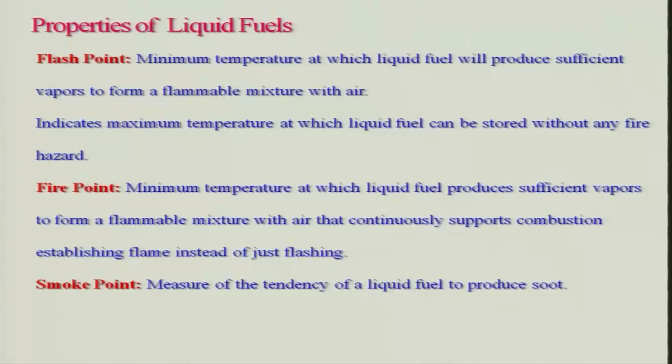Another property is known as smoke point. It is a measure of the tendency of liquid fuel to produce soot. Similar things are utilized for gaseous fuel as well. There will be a smoke point where it starts smoking, and smoke must be avoided.